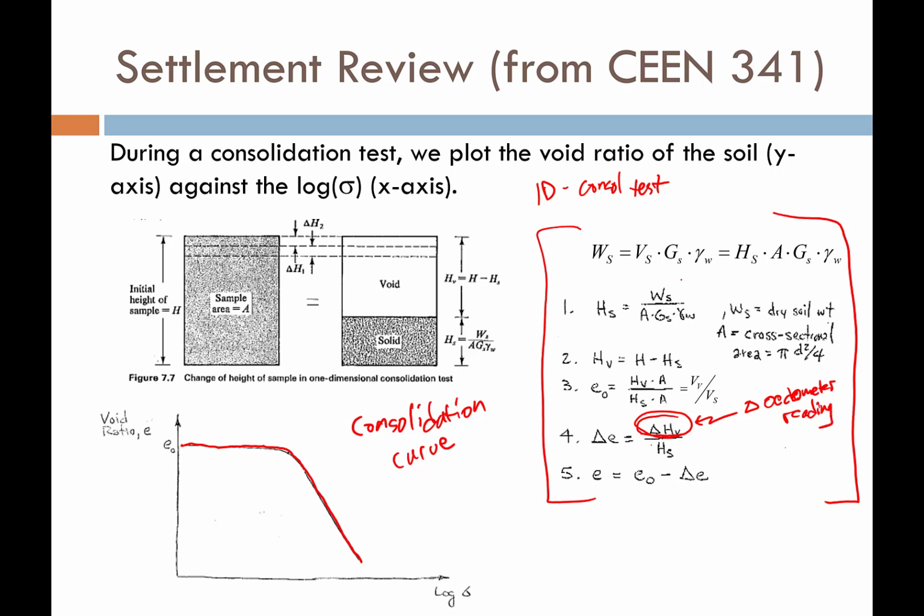And the height of the solids, this is something that you calculate from your phase diagram, stuff that we learned in elementary soil mechanics, and the weight of the solids as well. But all of this information will be helpful to you so you can create your traditional Terzaghi consolidation curves.